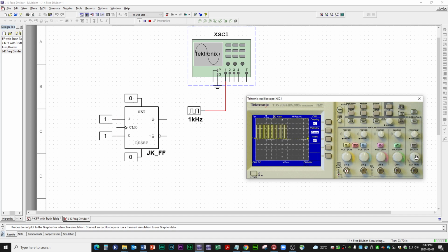Now let's stretch the time per division. Right now it's 2 milliseconds per division, and it's showing us the signal too dense. Let's magnify the way the signal is displayed a little bit so you can see it more comfortably. We're going to change the time per division, so it's 200 microseconds per division right now. What else do we need to do? We need this thing to stop scrolling. How do we stop this thing from scrolling?